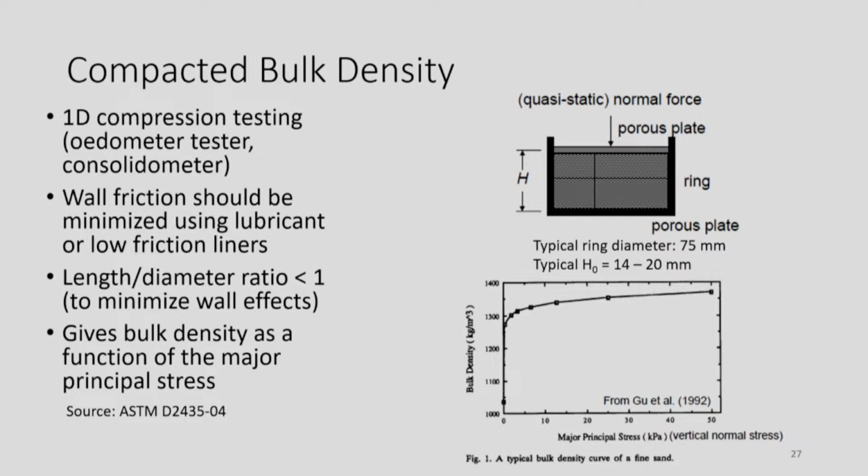Okay. Or, most commonly, you use powders, like magnesium stearate, which is very common. It's a powder, so what they do is compact with magnesium stearate first. It softens and smoothens the wall, and then you remove the magnesium stearate compact, put in the actual powder and compact. Then there will be very little friction.